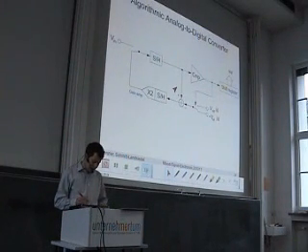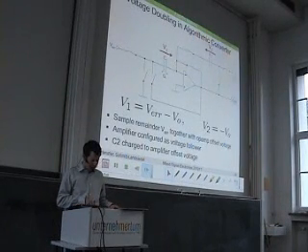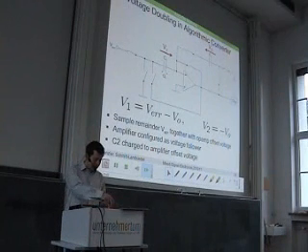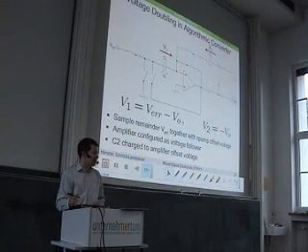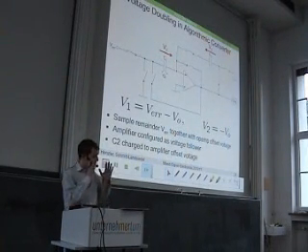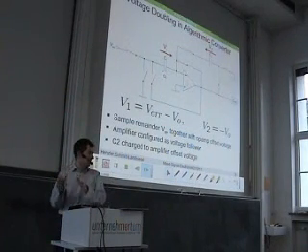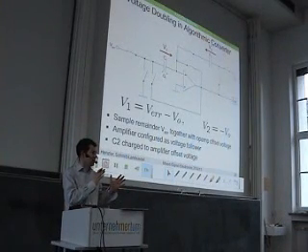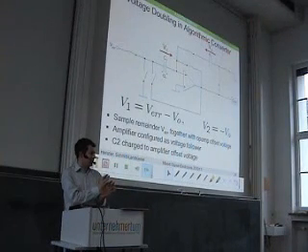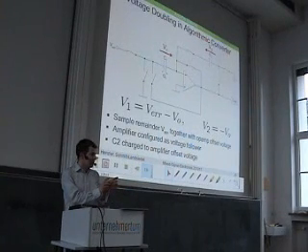And I placed an example for an x2 switched capacitor circuit in your slides as add-on material, and I recommend that you go through this circuit. Well, the basic idea in this circuit is to sample the input voltage, take the charge that you have on your sampling capacitor and store it somewhere. And then sample the input voltage again on the same cap. And at the end, combine these two charges. So you sample the input voltage, you sample it again, and then you combine the two charges.